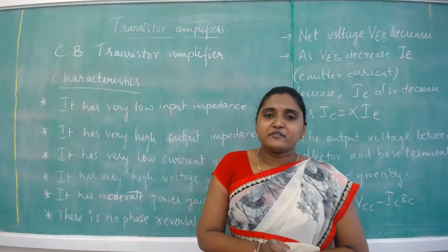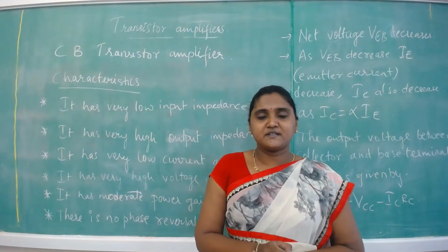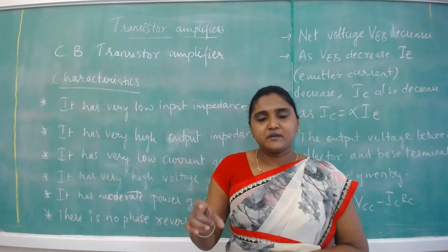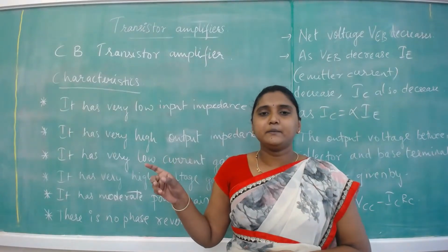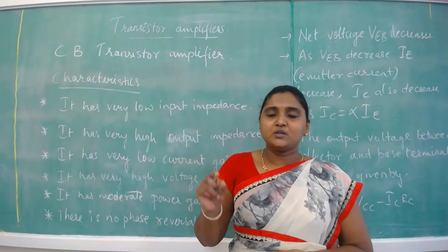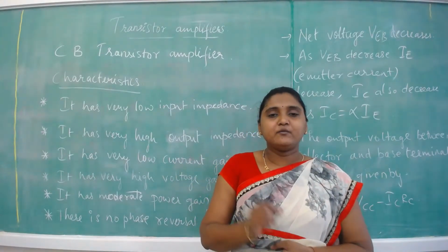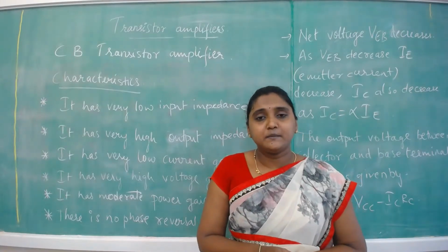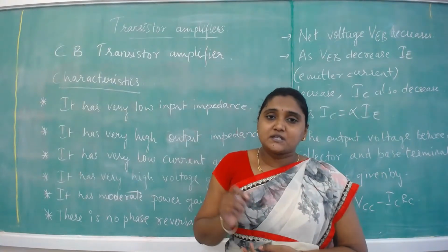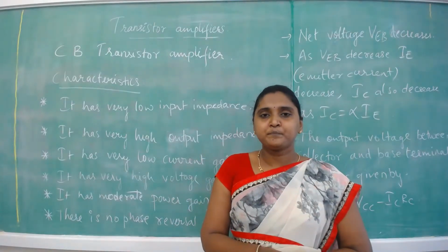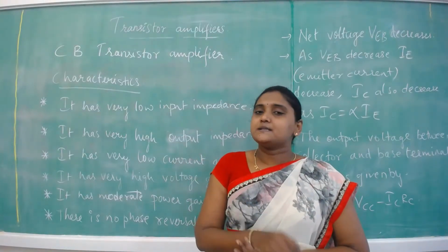That's one of the reasons to use gain in decibels. Then when we use multiple stage amplifiers and want to compute the total gain, individual gains are just added when the gain is represented in dB. Whereas in the normal representation, the total gain will be the product of the individual gains of the stages. This is the second advantage.